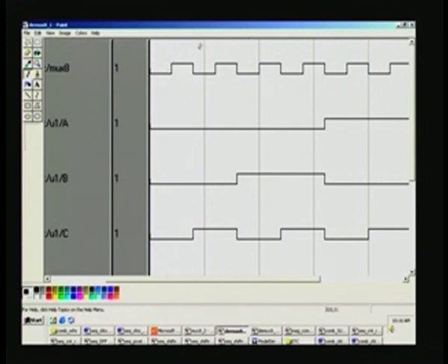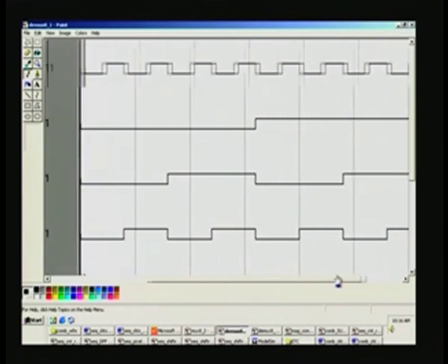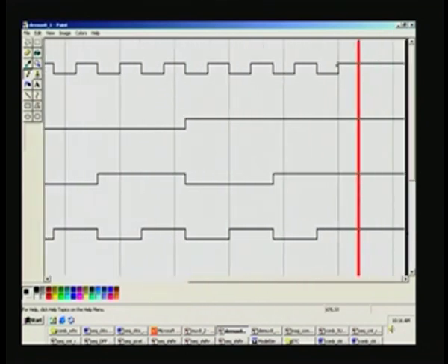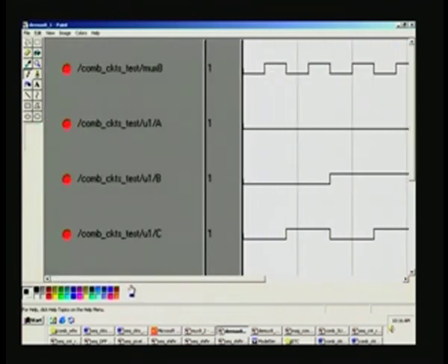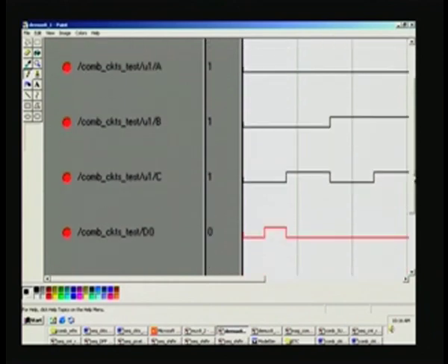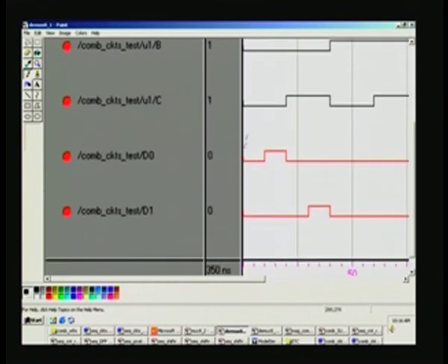This is mux 8, I0, I1 and so on right up to I7, which was flat on top here, and so what we expect here is D0 through D7 as the output for the demux. As we said before, I0 was just this waveform, and thereafter it was flat 0. So naturally if it is working correctly, you should get the very same waveform, you should recover back your inputs, and let us see D0 first. So that is precisely what you have here.